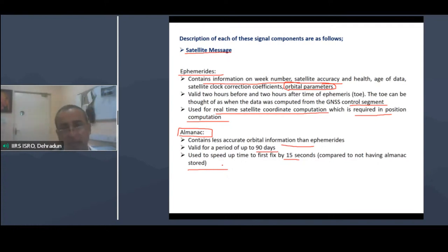The carrier measurement is a more accurate approach than code measurement. According to the hardware and its setting, we can select which type of solution it will provide, but automatically it goes for code measurement or carrier measurement depending upon the configuration of the hardware. If the hardware is capable only of code, it will not use carrier information. But if it has the capability to use the carrier information, then it will work for carrier. But if it is not able to resolve the ambiguity, then automatically it will switch to the code measurement technique.